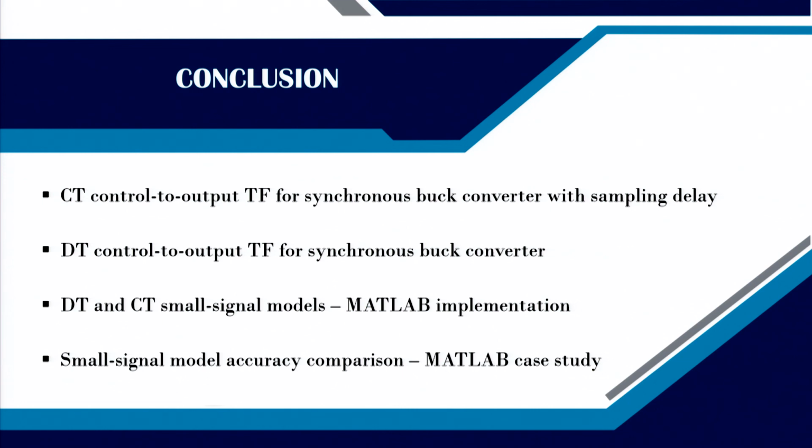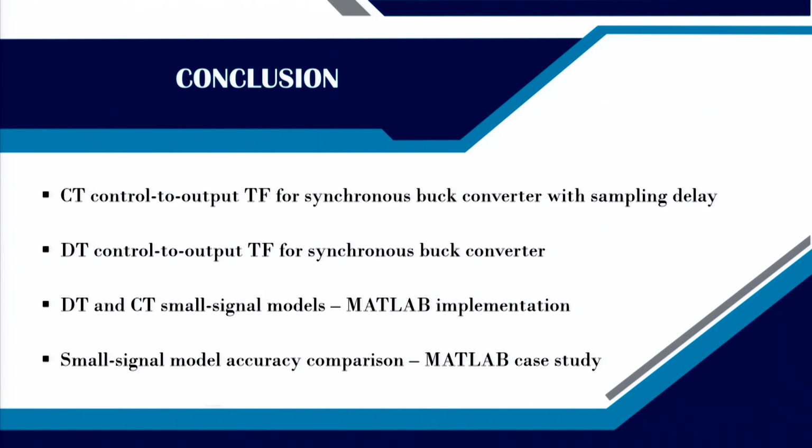So that is why, in summary, we can say the continuous time small signal model with delay will be a very good solution to start designing the digital controller, because we can get physical insight in terms of poles and zeros. But we will see in the subsequent design class that we need the discrete time model to predict stability. We can even predict various nonlinear phenomena, or if you want to do some kind of spectral spreading, the discrete time model is very effective. So in summary, I think we have understood all the modeling aspects, we have validated using MATLAB, and in the subsequent lecture we will be talking about the design process.